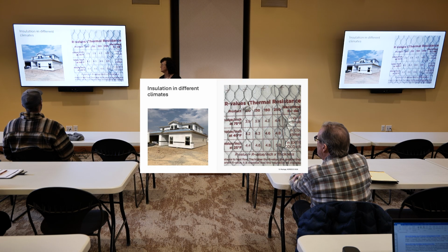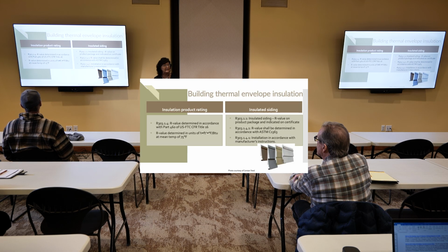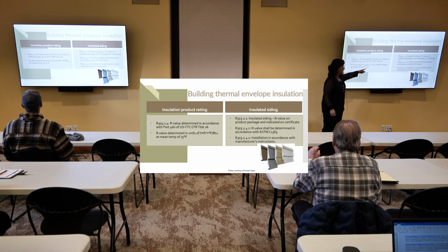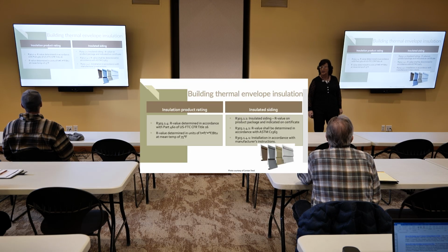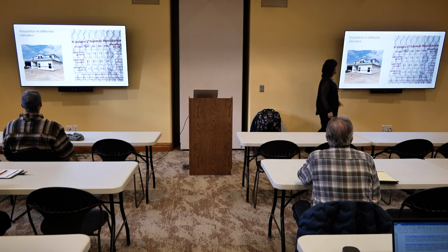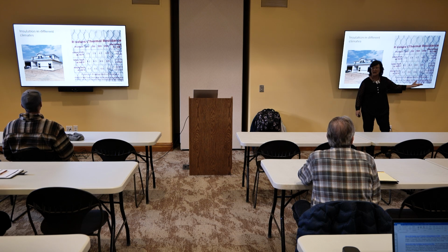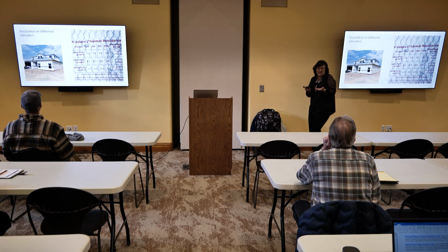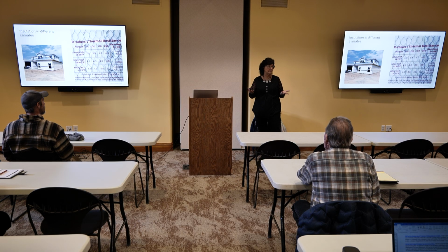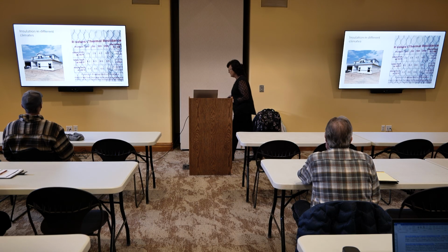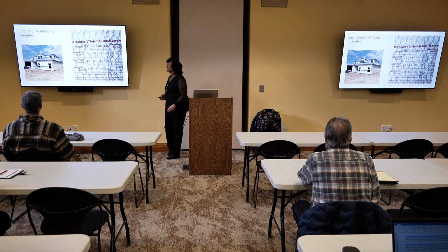The energy code we'll see here, in the energy code it tells you when you're evaluating R value, you have to do it at the 75-degree temperature. Right? So if I go back here, at the 75-degree temperature, I'm only getting that 4.4 instead of the 5. Not a huge difference, but if I'm trading some stuff off and I'm just passing by 0%, it might not be the right number, right? So just something to keep in mind.